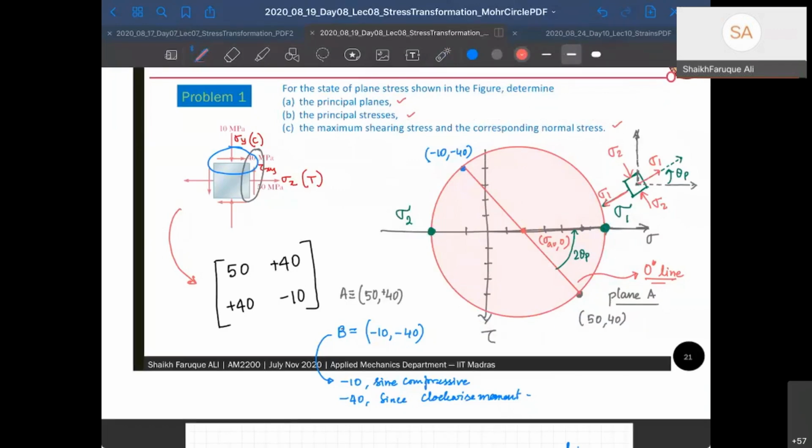So in the element, I have to represent it, right? Sigma 2 is the value there. For example, in the diagram given in the problem, 10 MPa is the magnitude given, and the direction is given by the compression. So that's the magnitude here. Should that be mod of sigma 2? Well, if you insist, yes, I can write mod, but this is how you represent it in engineering. You don't write mod, you write only the value and give the direction.